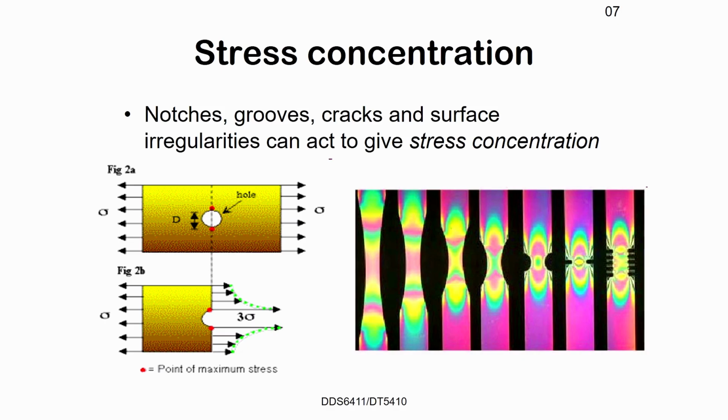We have already mentioned the effect of irregular geometry on the stress distribution. So whenever you take out material, like making a hole in your teeth, the cavity prep, the neighboring remaining material will have to take up more load. You're missing your partner next to you. No one's going to share the work, so you have to take up more work. So whenever you have a discontinuity in geometry, you're going to have so-called stress concentrations. Those local areas have to take up more force.